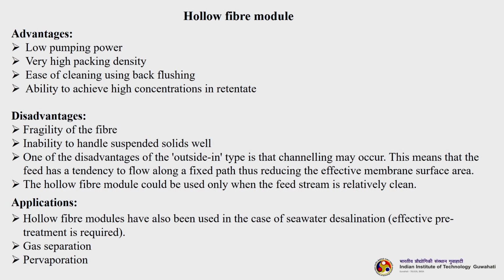So, the advantages are low pumping power, so it actually saves energy and cost, and very high packing density. We saw in an industrial establishment how lakhs and lakhs of hollow fibers are fused together in a single module. That means you can understand that in a very small floor space we can have so much membrane area. Then, ease of cleaning using back flushing. So, cleaning is easy here, we can use back flushing to clean the membrane as well as the module, and ability to achieve high concentration in the retentate. So, you can have very high concentration in the retentate.